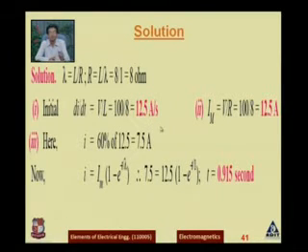That means per second, 12.5 ampere will get added in the circuit. So how much is the steady state value or the maximum value? You can find the maximum value by the equation Im is equal to V by R. As you know, the battery is 100 volt and the resistance is 8 ohm, so it will be 12.5 ampere. Now 60% of 12.5, what is it? It is 7.5 ampere.